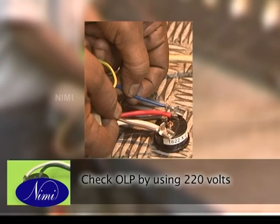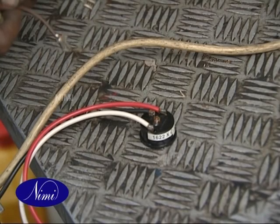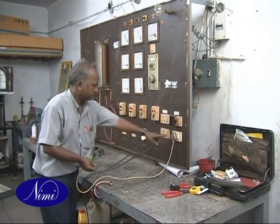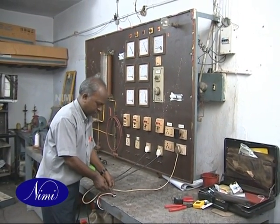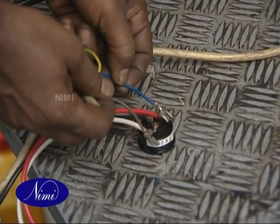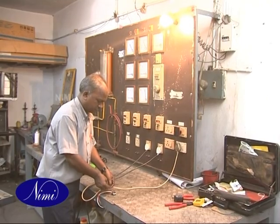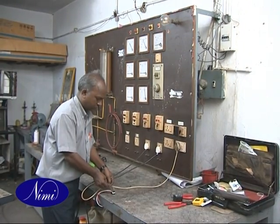Check overload protector by using 220 volts. Take an overload protector. Take a test lamp, plug it in the test board and switch on. Touch one lead to OLP number 1 and the other to the second and third terminals. If the bulb glows, the overload protector is good.